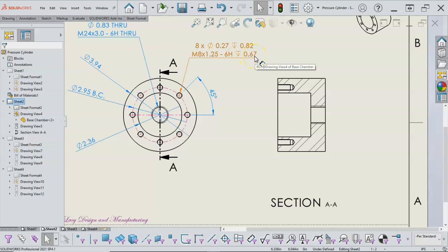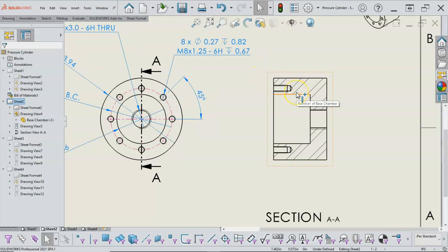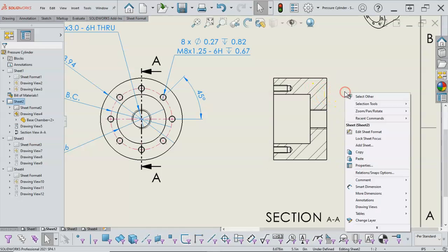So when it's attached to the thread, it's assumed the thread length, and really what you're allowing for is the machinist could, if it's not a very efficient use of the drill bits and the machine, but if for whatever reason the machinist decided they wanted to drill almost all the way through as long as it didn't break out, legitimately they could do that, even though it isn't a best practice.